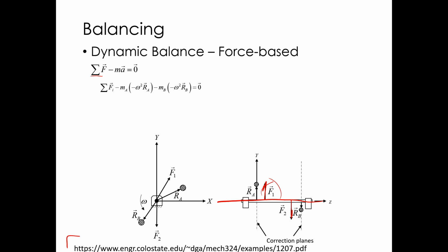Important thing to note here on sign convention of these forces. In this equation, this is the force on the body we're trying to balance. That's different than the force that our bearing transducer would measure. The bearing transducer would measure the force on the bearing. We want the force on the shaft. So for the purposes of this derivation and the problems I give you, I'm going to give you the force from the bearing onto the shaft.